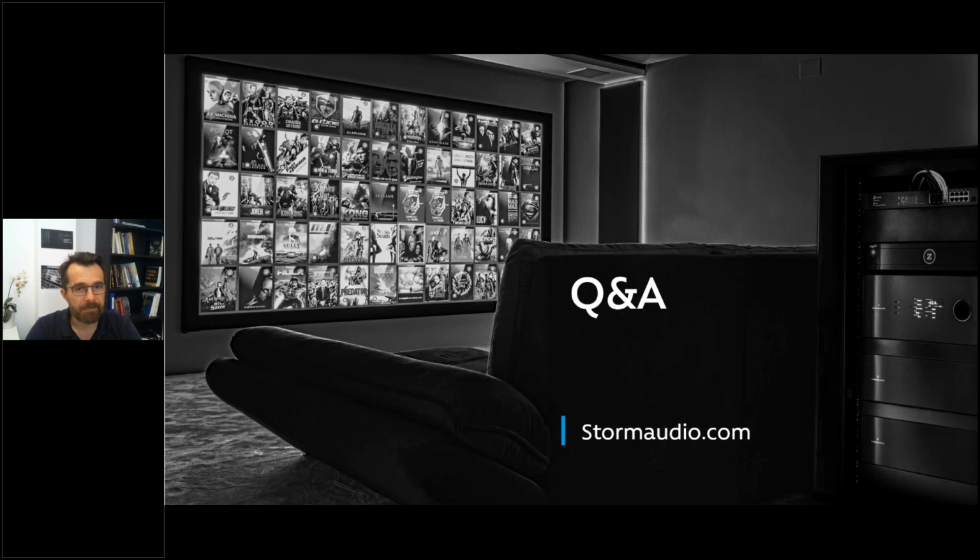The other subs, if they are capable, you can have them supporting to as low as that. But just keep in mind that actually, and this is why you might leave the infrabass out, ART will only work efficiently from 20 Hz to 150 Hz. Frequencies below 20 Hz are not considered within ART, they are simply bypassed.